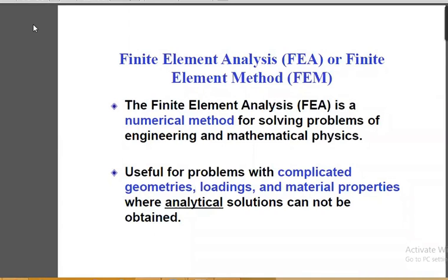These limitations are that the cross section of the part or rod should be uniform. It should be uniform means your cross sectional area should be uniform throughout the section. Then and only then can you apply your strength of material theory to find the stresses acting on that material. But if I change the cross section to a tapered geometry, in that case you cannot apply these